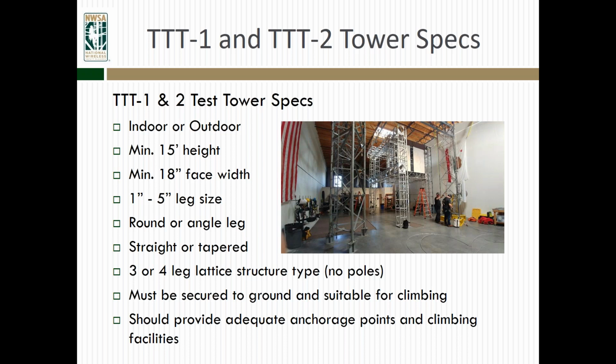So depending on the tower type you have, it needs to be able to be protected with Y lanyards, right? We're not going to be using a safety climb on it or a vertical lifeline, so it needs to provide adequate anchorages for their energy absorbing lanyards, as well as positioning devices. It should be fairly easy to climb. It doesn't have to have a designated ladder, though sometimes with larger self-supports, the climbing can be a little bit trickier. So think about your tower and try to make it easy to climb on with adequate anchorage points for a reliable exam site.